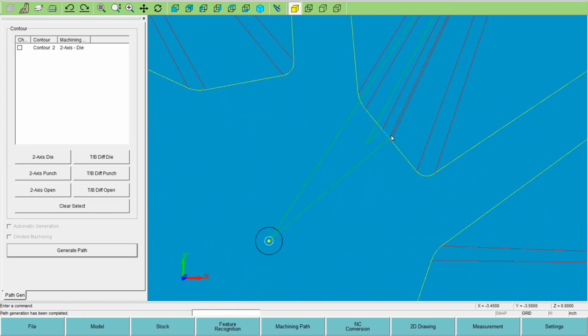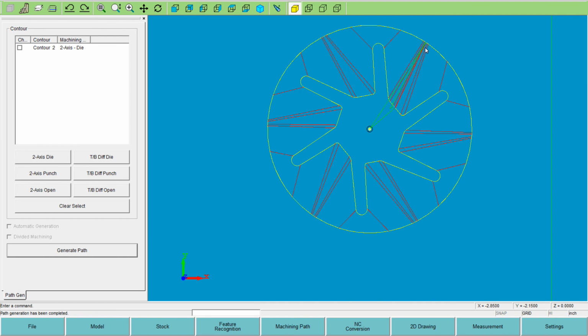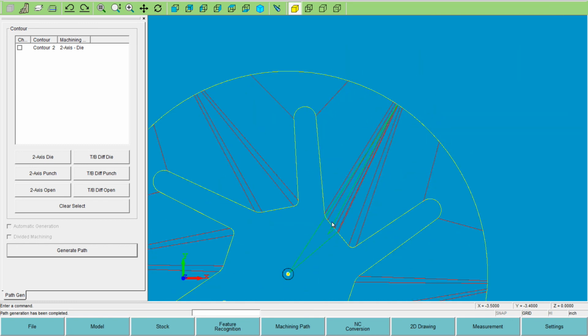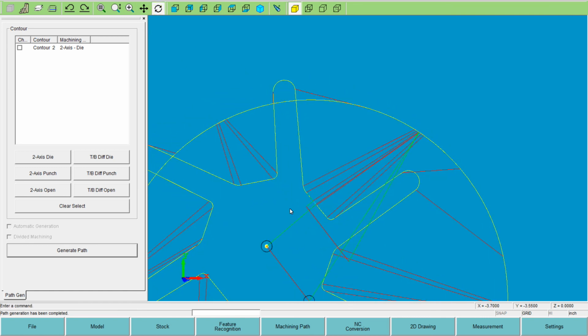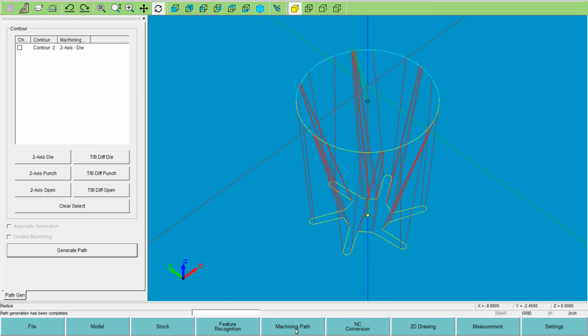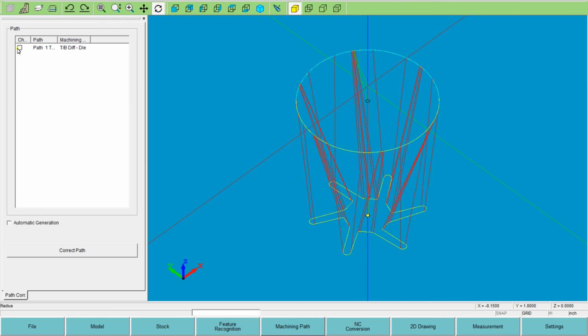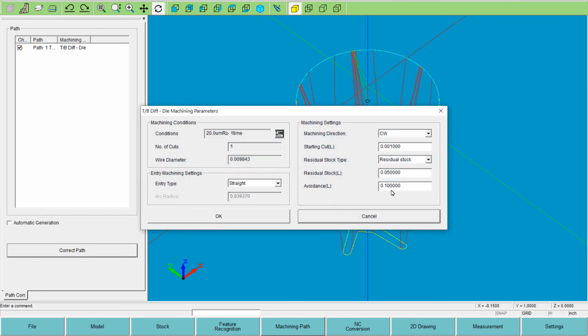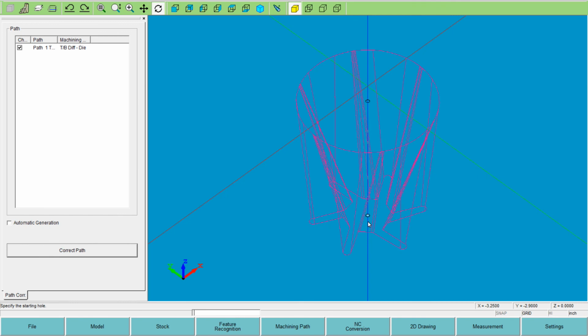So to put that one perpendicular off of this shape, this is coming at some weird angle because of these match lines are tapered kind of from the bottom inward. So it gives you kind of a funny move at the top. So it'll be fine because it backs up far enough. Let me explain it a little bit better with a different length of the tab. Let's go path correction. Maybe you didn't quite understand what I was meaning. So we'll put a residual stock, your hold on tab, of like a 1/2 inch. So it'll be way back off of that shape.